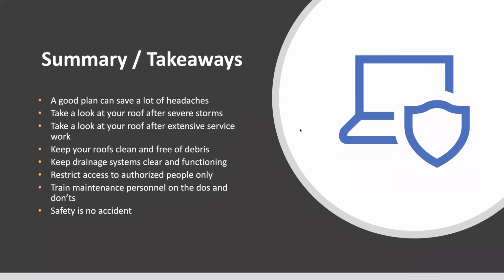Always keep in mind those events that should trigger you to want to take a look at your roof after a service event, a big storm, or anything like that. Keep those roofs clean and let the water flow readily off the roof, and restrict access. You don't need more traffic up there than necessary. And if you are up there, please do get some training. You can lean on people like myself to get you on the right path there. And of course, safety is no accident.